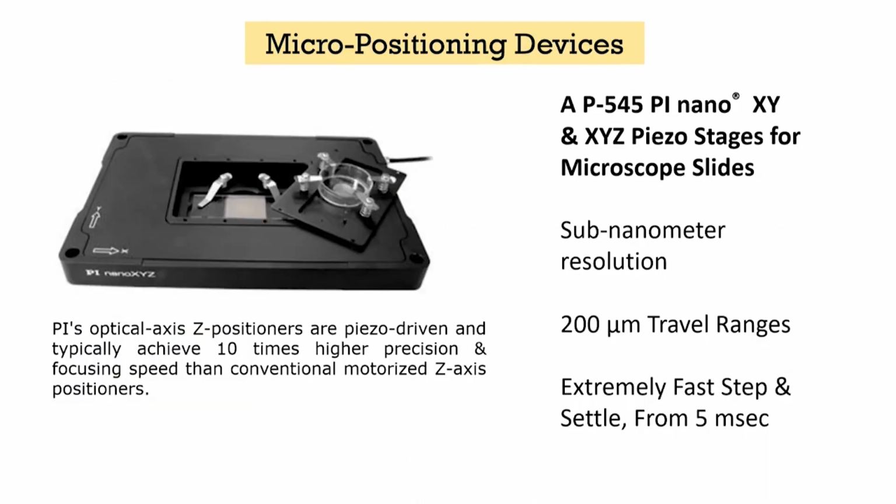Another application where piezo stacks are used is high precision micro positioning devices. This is a very common equipment in different types of high precision manufacturing and machining, as well as for microscopes, confocal microscopes, etc. Here they use a P545 PI nano, where the travel range is 200 micrometer, but you can change this extremely fast, within 5 millisecond, and the position you can control very well.